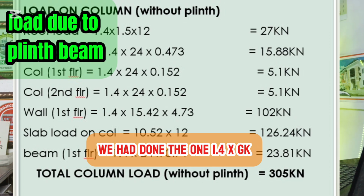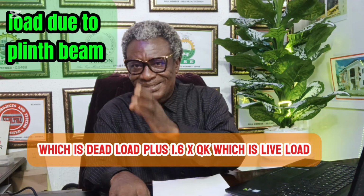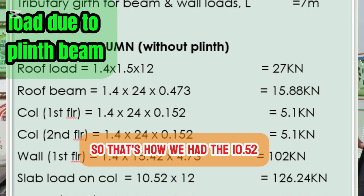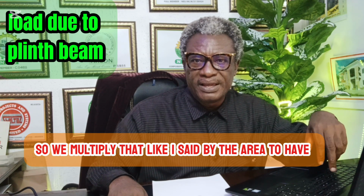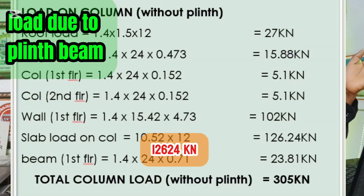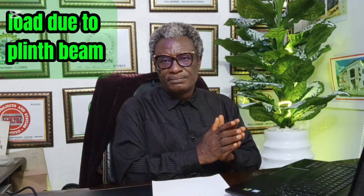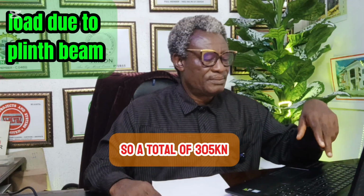We had done 1.4 by GK, which is dead load, plus 1.6 by QK, which is live load. So we multiply that by the area to have 126.24 kilonewtons. Then the load from the first floor beam. So a total of 305 kilonewtons.